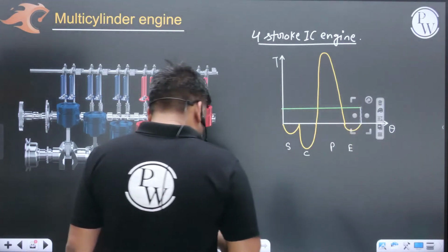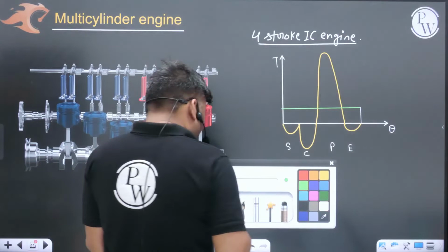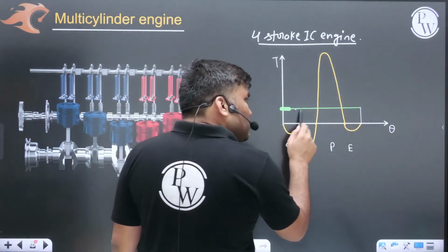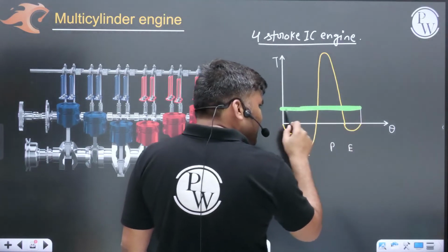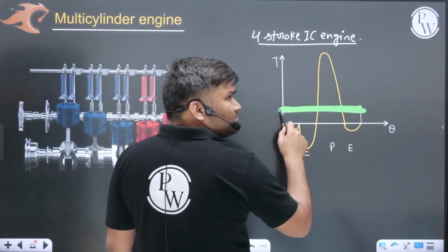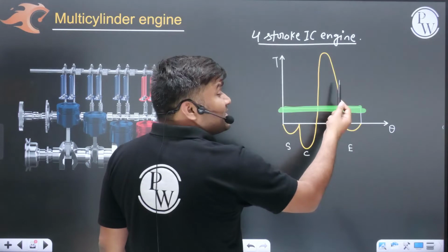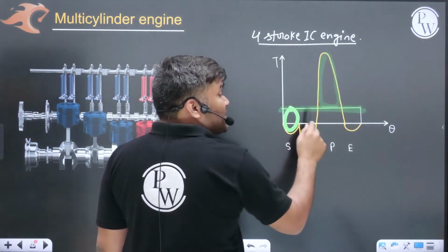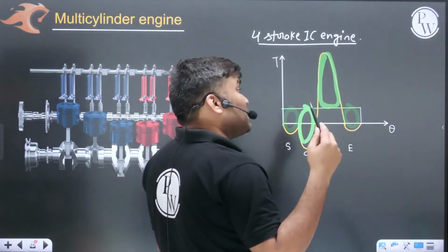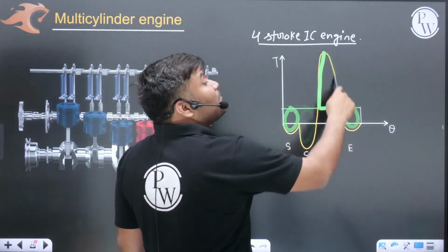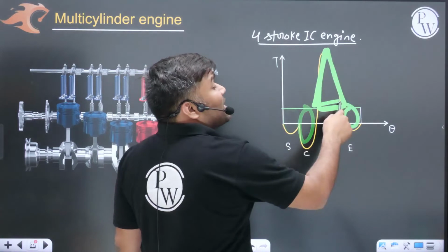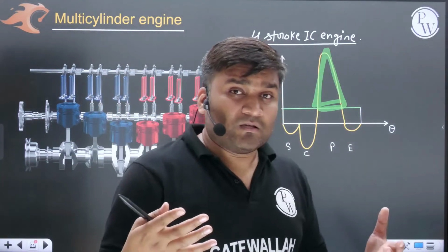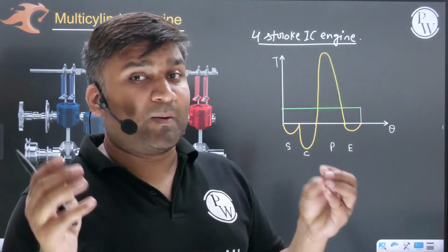Okay, if you connect the flywheel, what will it do? Sir, the flywheel, this is the mean torque and the resisting torque is also exactly the same, right? Same magnitude. Now if you connect the flywheel, the surplus amount of energy the flywheel will absorb, and in the rest of the places the flywheel is going to supply energy. Now can you feel this big amount of energy your flywheel has to absorb? The larger the amount of energy the flywheel has to deal with, the more inertia of the flywheel will be required.